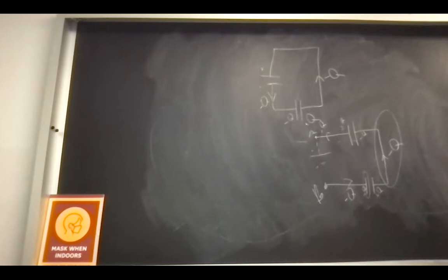So I know that's a lot. If you want to jot it down: when the switch is open, the circuit is broken, the plates are neutral, no charge going through. That's why we set it to 0 in the initial scenario. However, with the switch closed, negative charge will flow towards the nearest plate. And to counteract that, to keep this positive, the minus charge will flow off. And that means through the wire, there's a negative charge acting. That's why we plug in the negative 320 microcoulombs.